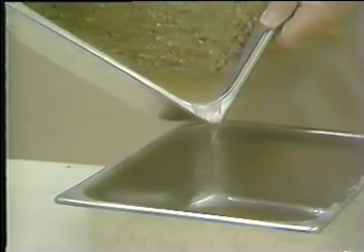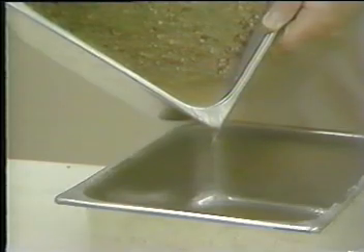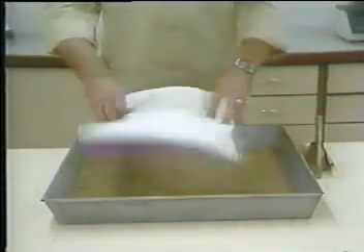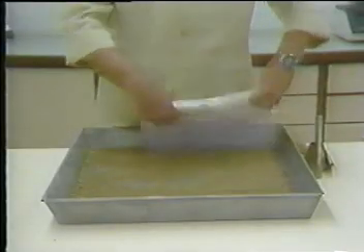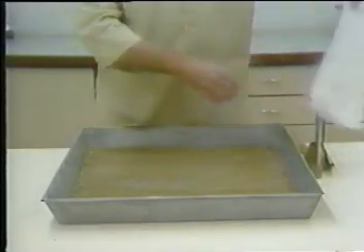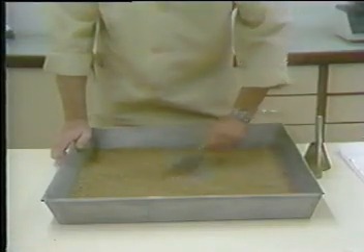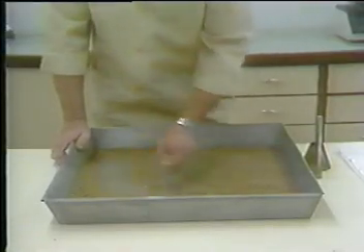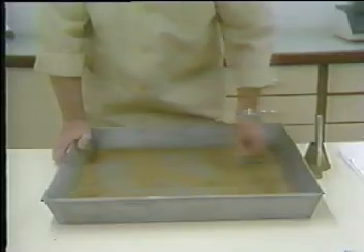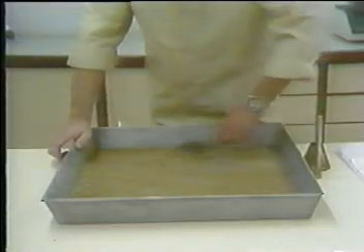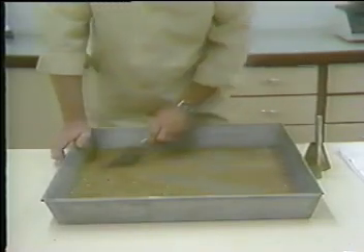Saturated surface dry condition is achieved by uniform drying of the test specimen. To do this, spread the sample on a flat, non-absorbent surface and expose it to a gently moving current of warm air. Stir the sample frequently. If desired, mechanical tumbling or stirring aids may be used to help the specimen reach the saturated surface dry condition. Continue to stir the specimen until it approaches a free-flowing condition.